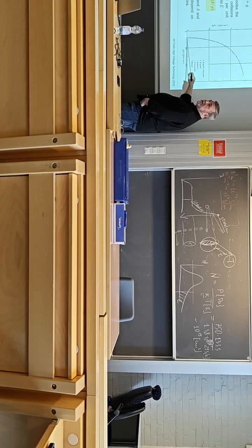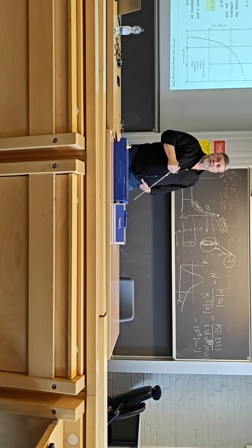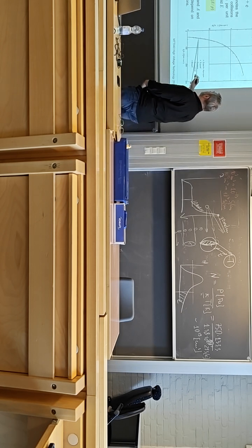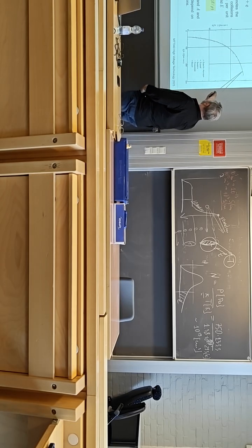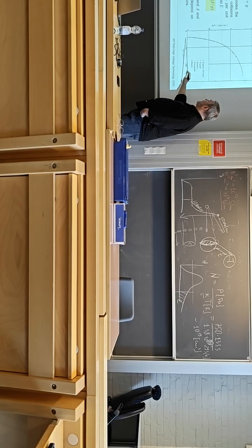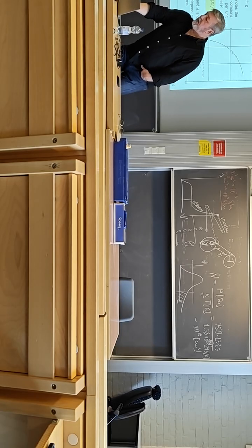Ionization starts here, right? Below this level of the field, nothing happens. No ionization is possible, the energy is low. Then when you increase the field, the number of collisions per unit of the path becomes higher and higher. At some point it saturates. But the important thing to remember is that there is a threshold which corresponds to the minimum energy for ionization.